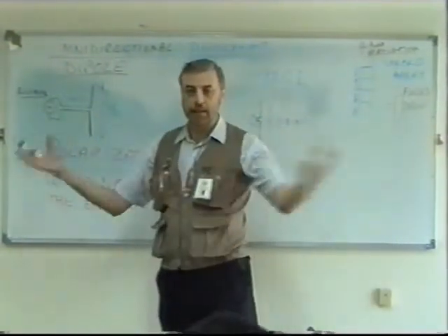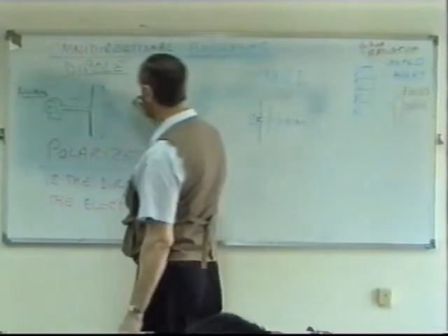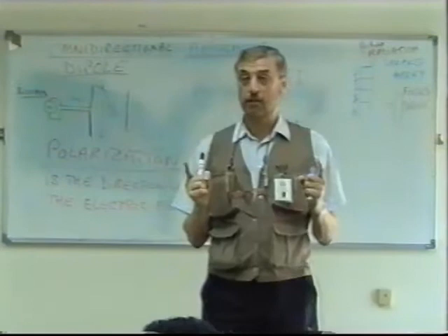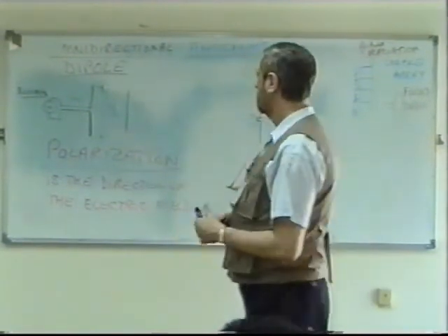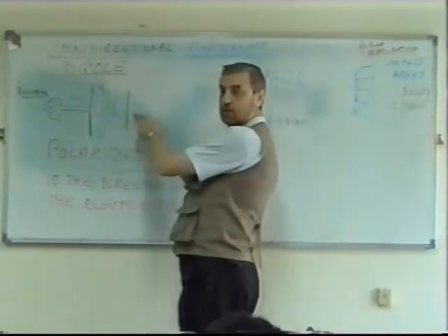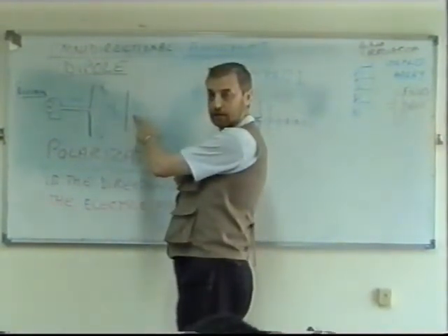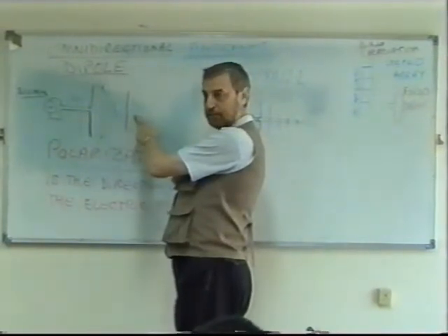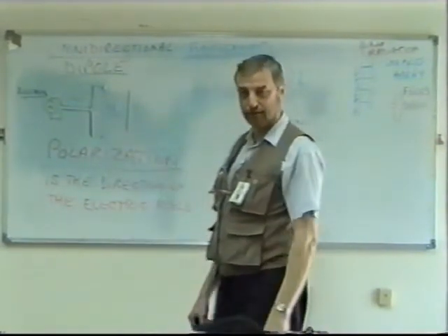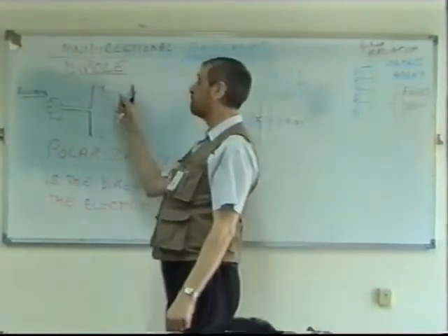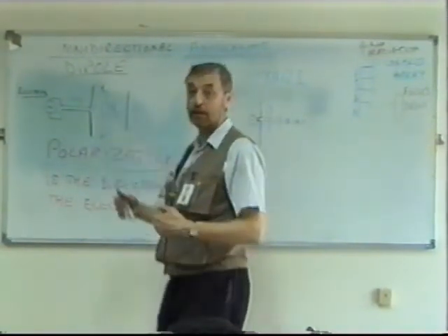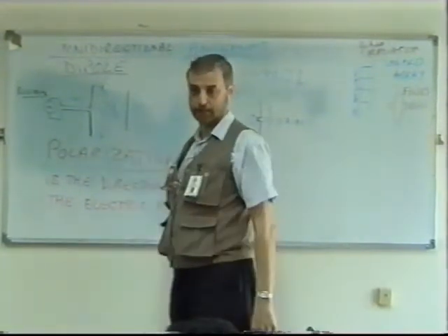It's radiating electromagnetic energy, okay? Now let's say I put a conductor here in front of it. Just an ordinary length of conductor. What's going to happen? Well, of course, the radiation from the dipole will induce electric currents in the conductor, like a receiver. The electric currents flowing in the conductor will re-radiate energy. And if the conductor was a perfect conductor, you could argue that all the energy received by that conductor will be re-radiated.